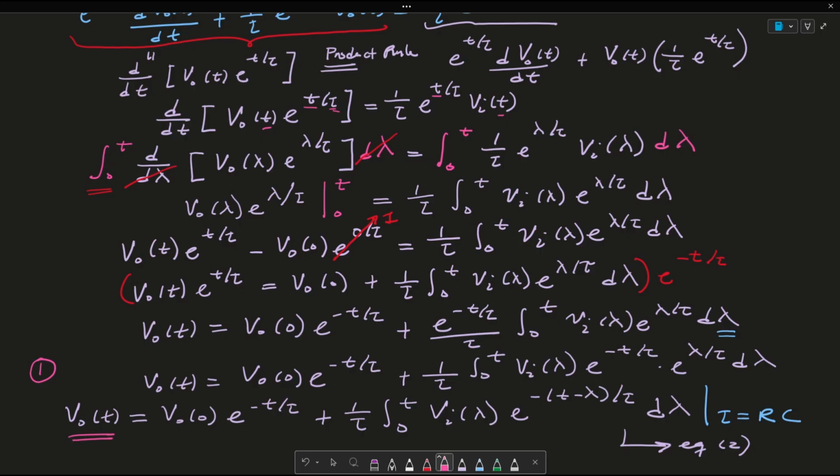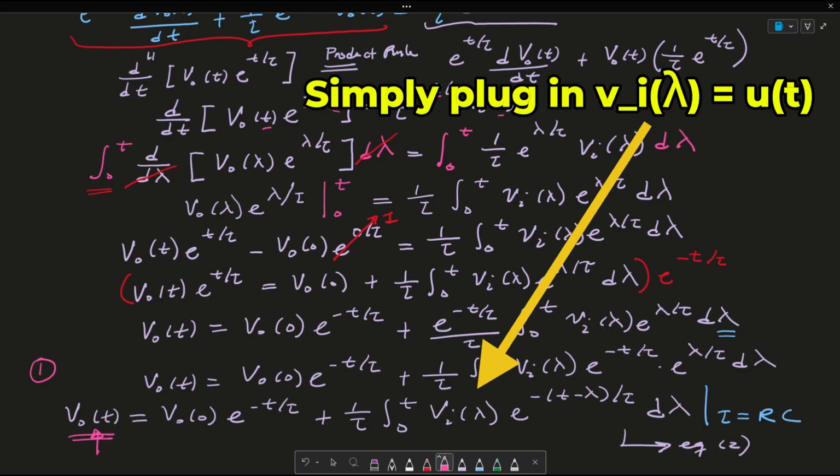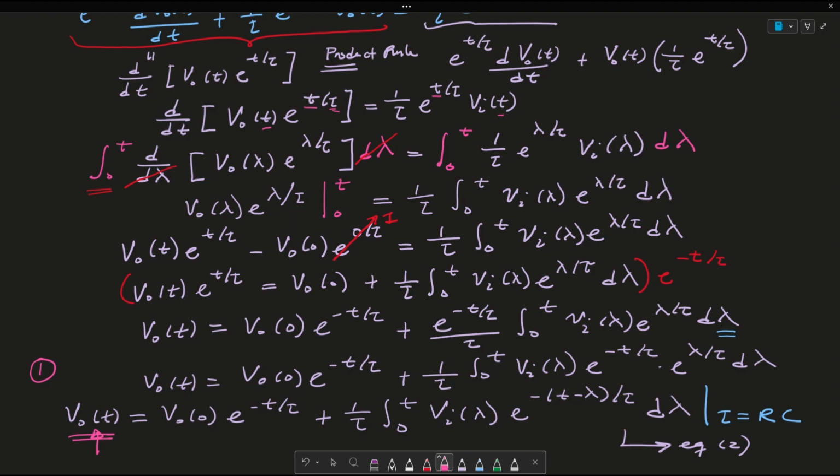And this equation is very important because if you've ever studied the step response of an RC circuit, embedded in this equation is the equation associated with the step response of the RC circuit. To see the derivation of the step response of an RC circuit, I have posted a video which I made in the past called Step Response of an RC Circuit Clearly Explained in the top right hand side corner of this video. And just as a general teaser, the equation that we talked about is using what's called the 5 equation. So final, initial, final, exponential.